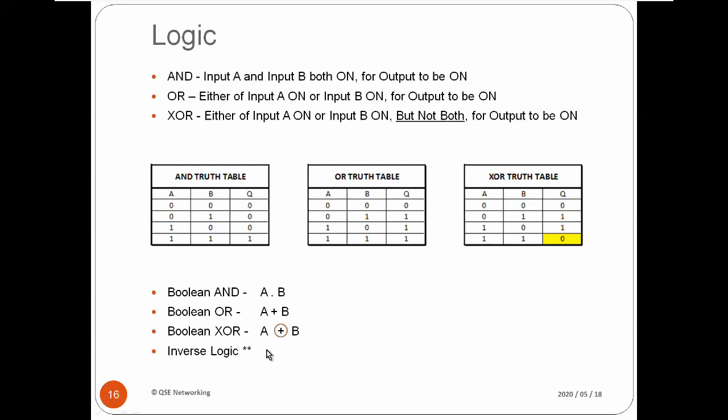Now, with Boolean, I forgot to put in your inverse logic. I meant to explain that depending on your logic, it is sometimes easier to do the inverse of what you think. So if you're saying it's A and B and not C and not D, it's sometimes easier to do the inverse and then invert the result.